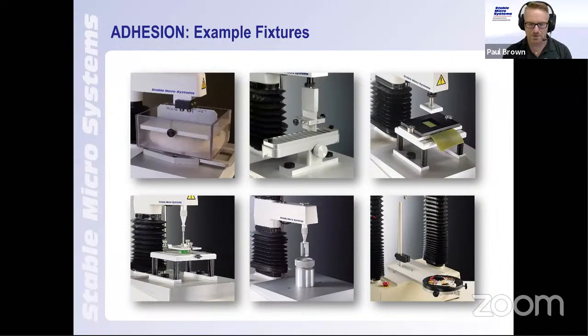Lots of different examples here, whether you're looking at dough stickiness. What you can see here falls under a number of different areas, because we're actually shearing the product. We're shearing the dough sample with a blade, but when we do that shear, we're also looking at the stickiness of the blade on the dough. We could do multiple passes on products, pastas, dough stickiness, confectionery type products as well. We can look at lots of different areas of adhesion. We call all those stickiness readings the adhesion heading.